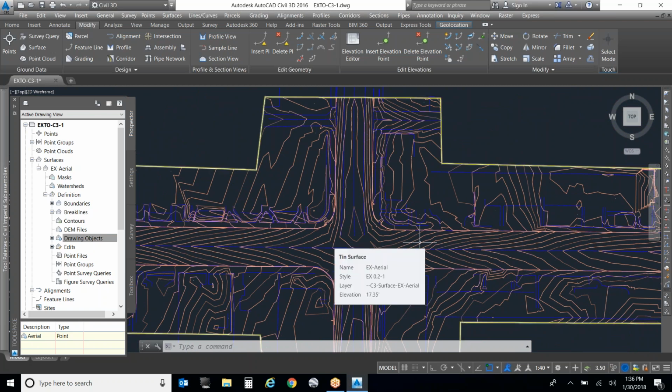you no longer really use the rule to set the invert. You actually just use the pipes from points. Correct. At that point, you're not setting the pipe from the surface. You're bypassing the rule. You're hard setting those invert elevations. And if you have more than one pothole, or even if you don't, you're setting that at its particular slope, if it has a slope. Because you're not just setting it flat, and if your alignment changes, then that projection changes as well.